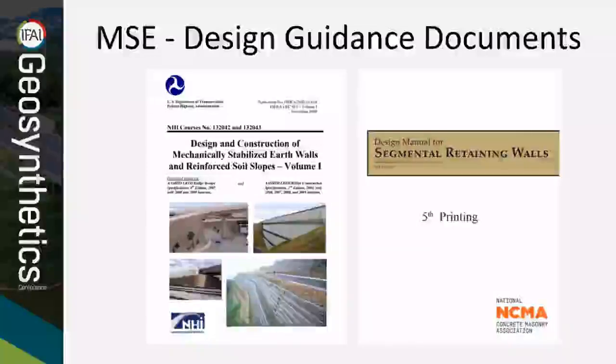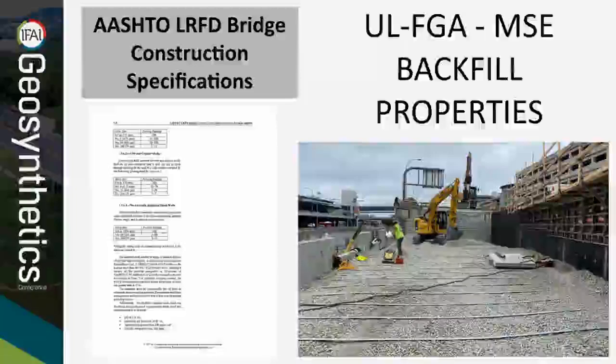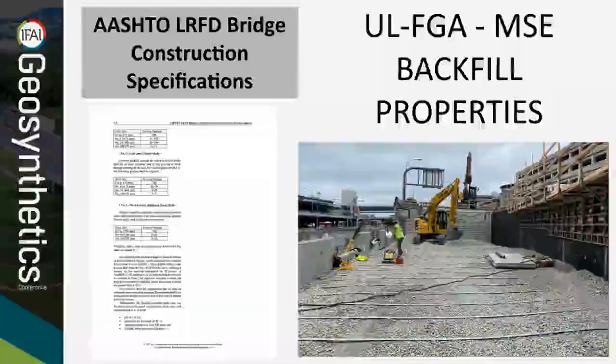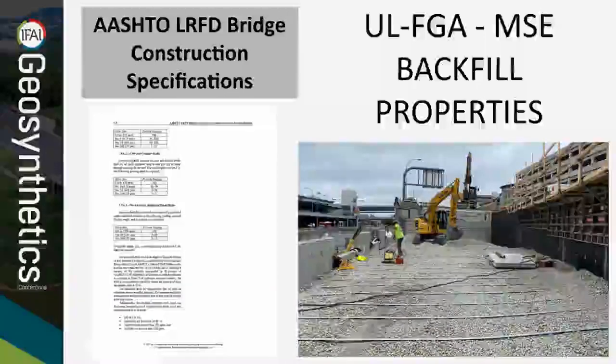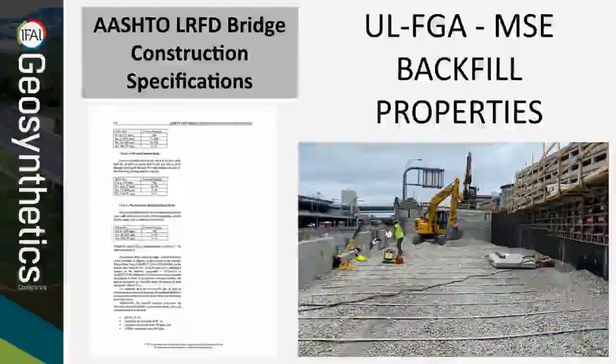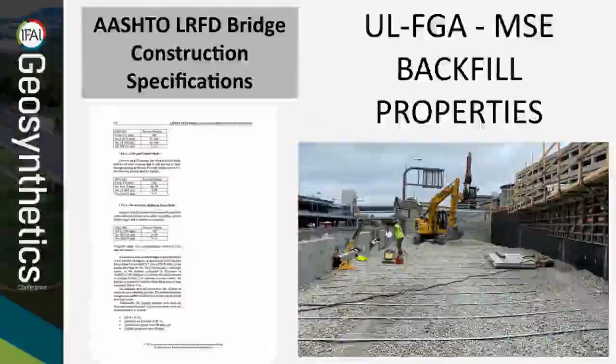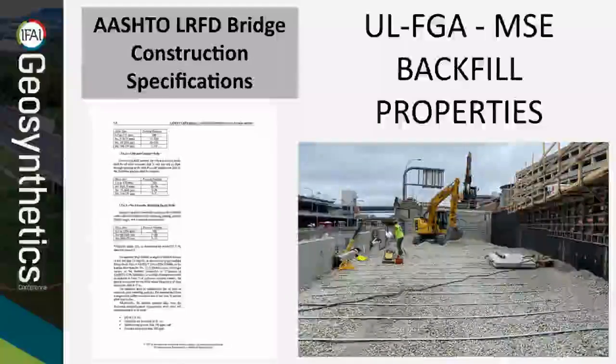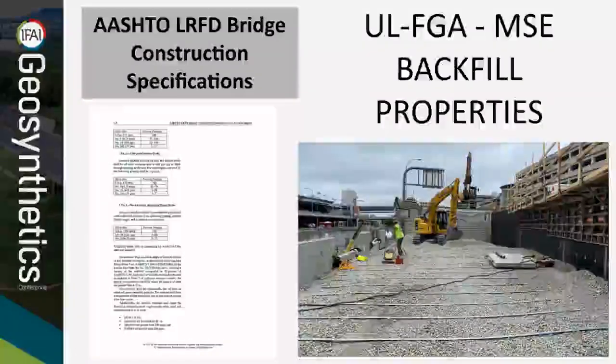There are 2 leading resources that provide design guidance on MSE systems. They are shown on the slide. In terms of MSE backfill specifications, again, there are numerous specifications that are available, but the most stringent has been published and put forth by AASHTO in the LRFD bridge construction specifications. So that is what I'm going to be comparing the properties of ultra-lightweight foam glass aggregate to. The photograph in the bottom right of the slide, you can see an MSE wall being constructed with galvanized steel straps.